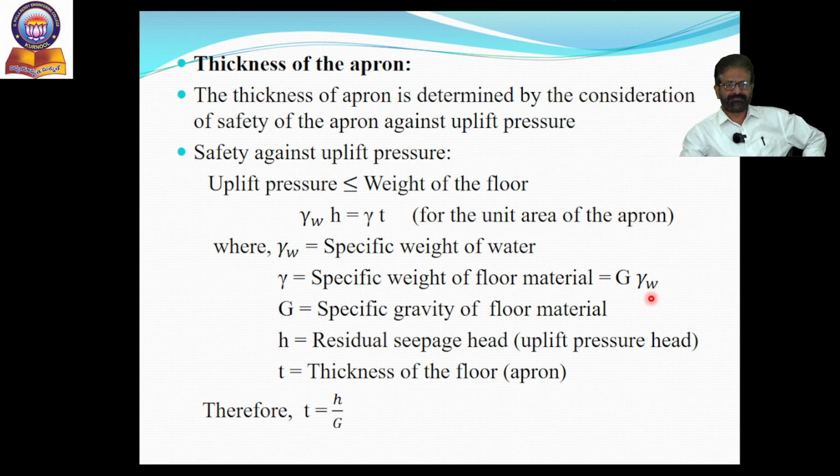And H is the residual seepage head or uplift pressure head. This is a very important parameter. Always we should remember while designing any solid apron, especially the thickness of the apron, that H is the uplift pressure head, which is also known as residual seepage head. Later I will explain what the residual seepage head is and how to consider it. This is the only parameter which is essential for fixing the thickness of the floor.